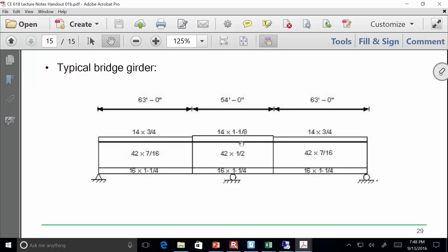In other words, if I put in a list every single positive bending region distribution factor and every negative bending region distribution factor and saw which ones were different, only about 2 or 3. Like all the shear ones are going to be the same, all the deflection ones are going to be the same, the lever rule and special analysis, they're all going to be the same. Just the moment ones, because the moment ones only have that kg term in it.